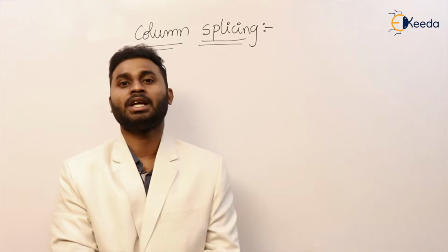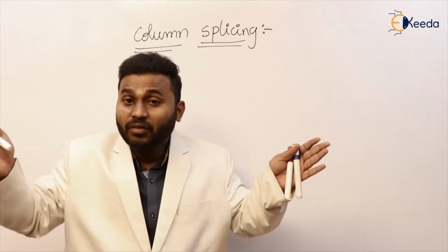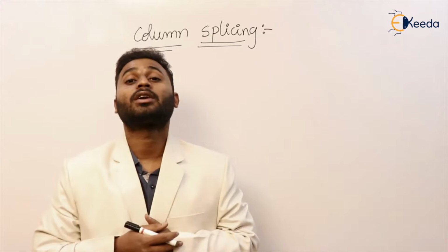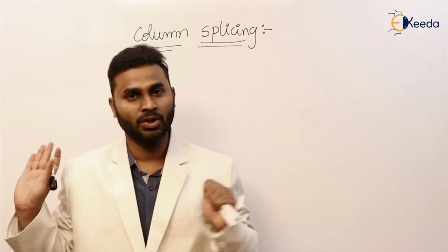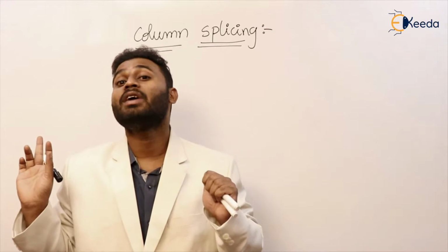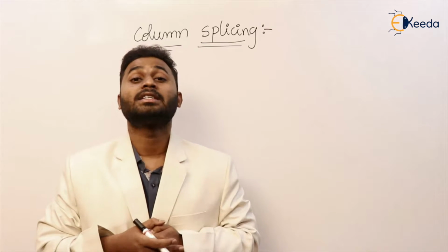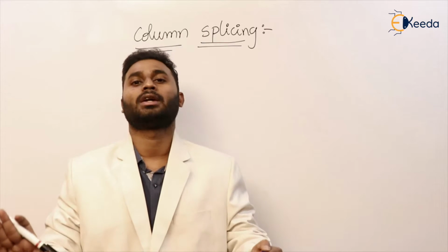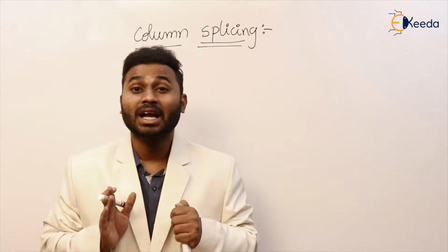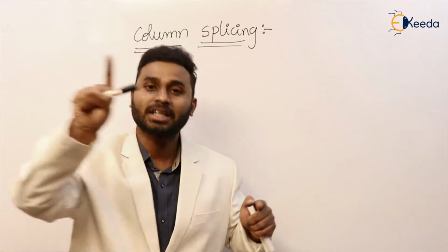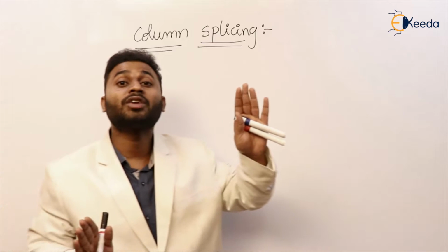Agree or not? Initially an individual channel will have one area, that is the gross area, which is mentioned in the steel table. But after making the connection, that column is known as a built-up column, and the gross area becomes twice in the example we discussed. So there we have increased the area. Whenever we make a connection for increasing area, such a connection is known as a built-up section. But whenever we make a connection for increasing the length, then that connection is known as splicing.